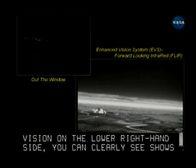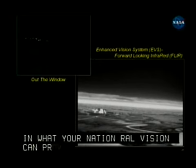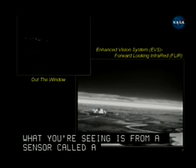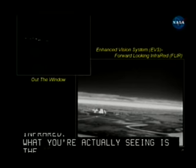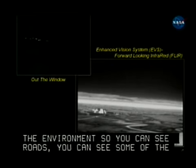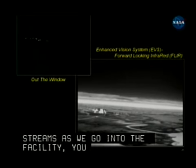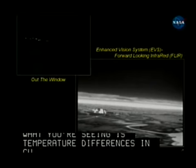What you're seeing in the enhanced vision system is from a sensor called a forward-looking infrared. So what you're actually seeing is the temperature differences in the environment. So you can see roads, you can see some of the streams as we go into Wallops Flight Facility, you can clearly see the runway information. So what you're seeing is the temperature differences in the cultural features, in the objects out in the environment.